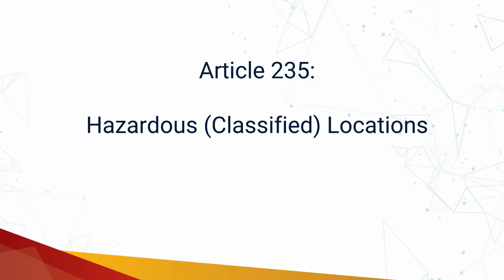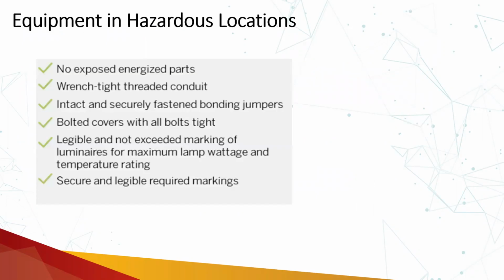235, it's about hazardous locations. No exposed energized conductors within the hazardous location where there is a chance of flame, ignition, or things like this. So if we have an exposed energized conductor, just due to some arcing event or any event, it can turn into a catastrophic failure.